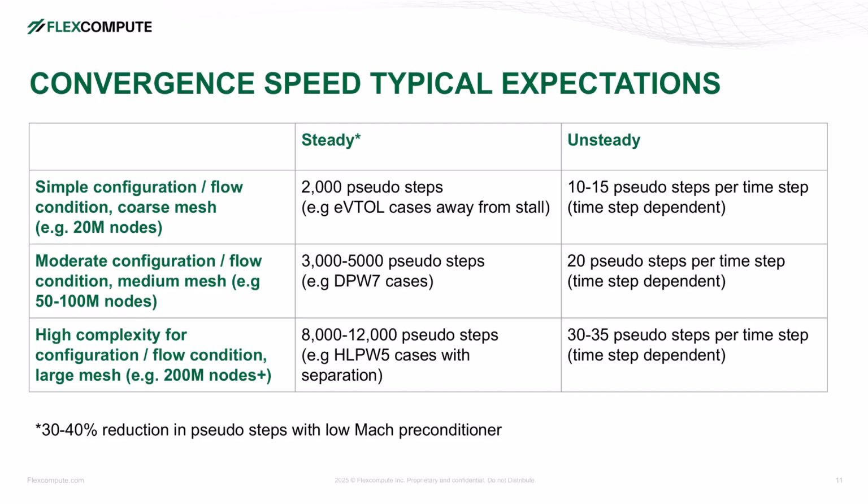For highly complex cases with large meshes, you can expect to need more pseudo-steps and more conservative CFL settings. Around 8 to 12,000 for steady and 30 to 35 pseudo-steps per physical step for unsteady.